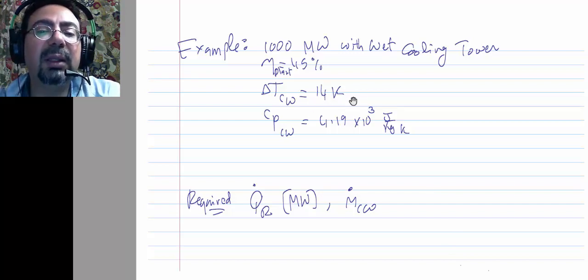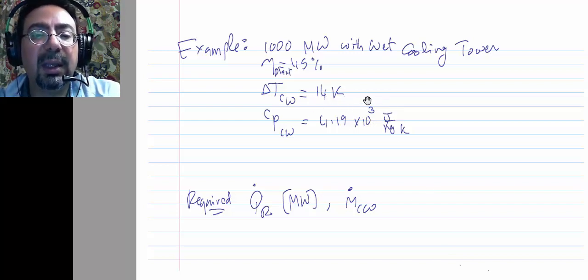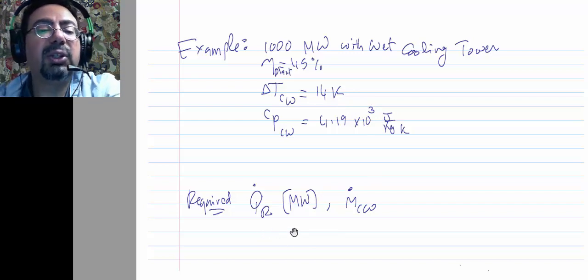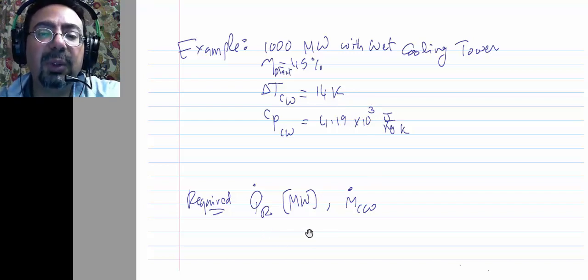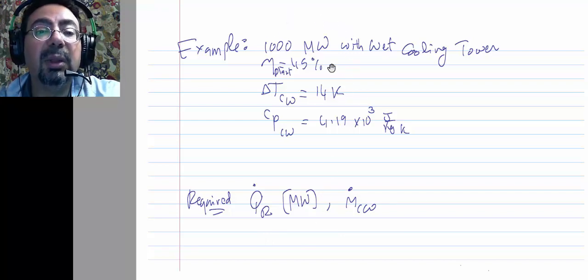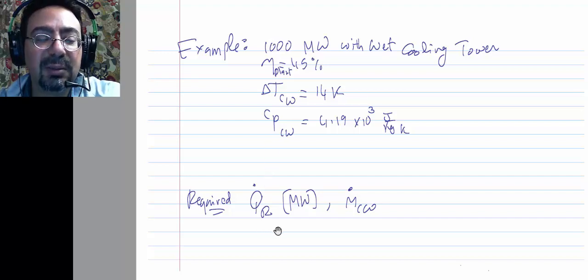So he can only heat it up 14 K. Alright? So first of all, he wants Q rejected. How much Q rejected? How do we do this? That is the work net, right? And you have the efficiency. So you can calculate how much is Q added, and you do subtraction, you get yourself Q dot rejected.